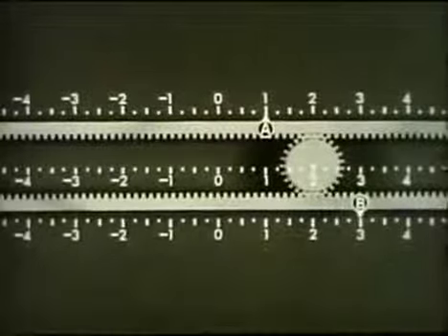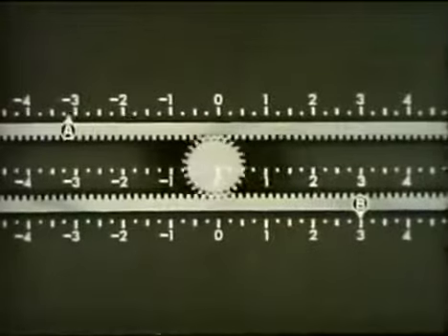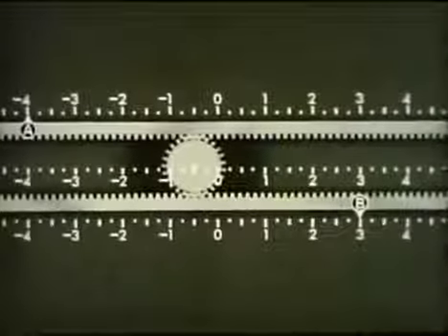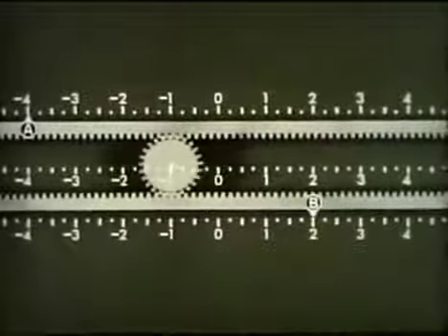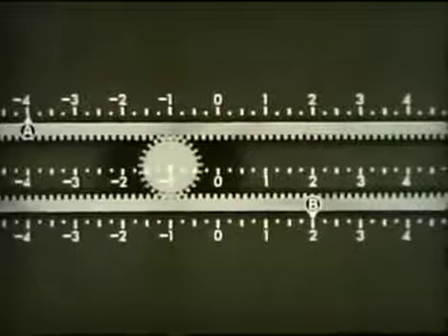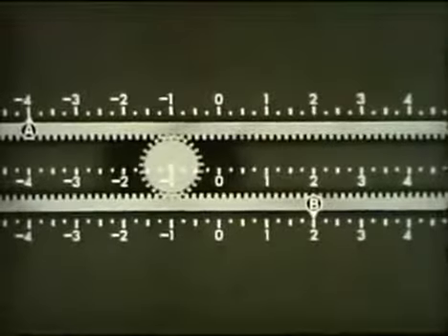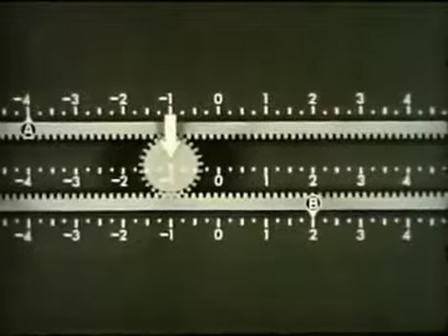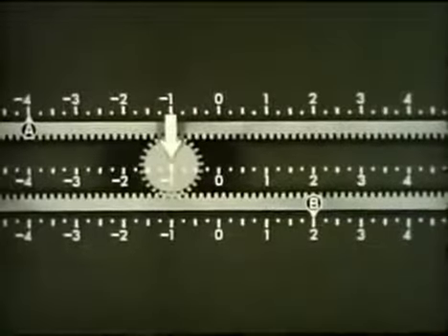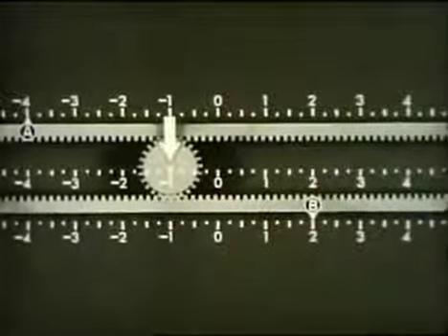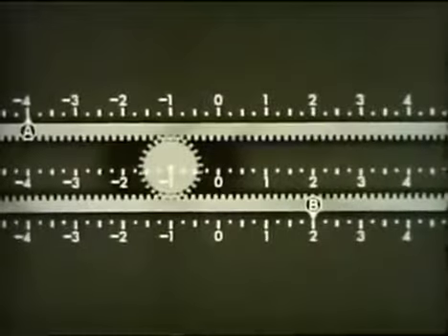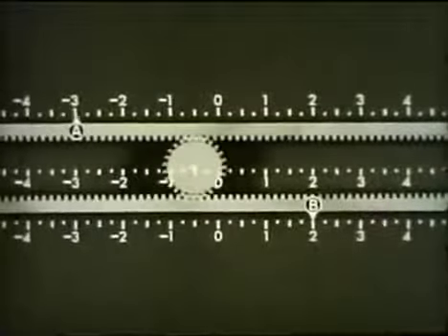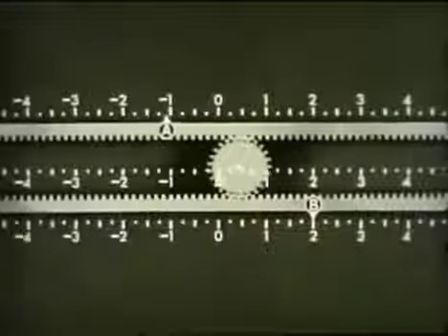As another example, move A to minus 4 inches and B to plus 2. The algebraic sum of the rack displacements is minus 2 inches, and the pinion center has moved to minus 1. Measured from 0, the change in the position of the pinion center is always half the algebraic sum of the rack displacements.